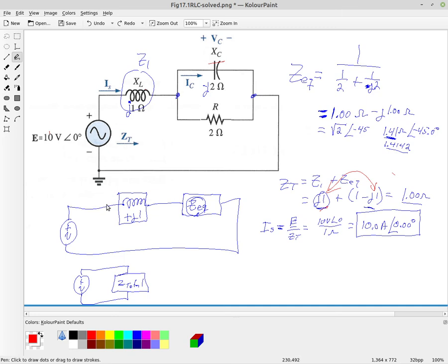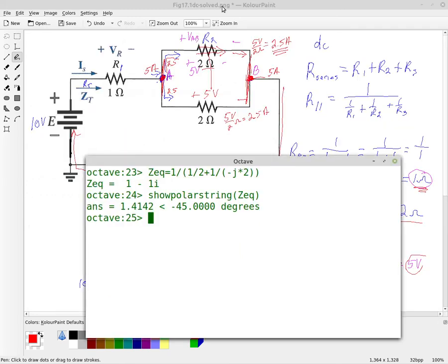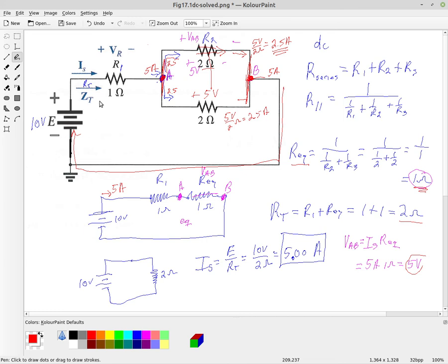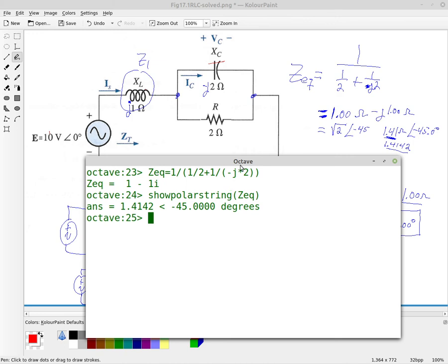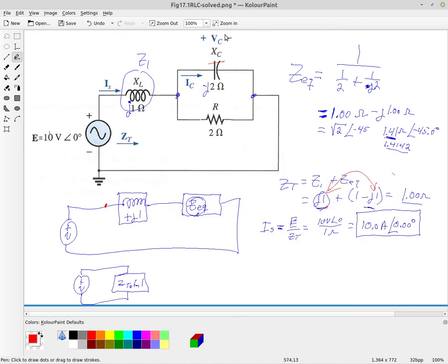Let's find out. We haven't actually done this before, but if you go back and look at the previous circuits, I didn't make a point of this. If you look at the voltage of this circuit, this is our original DC circuit, we did calculate that we had 5 volts DC across these resistors, and since we had 10 volts here, that meant that we actually had 5 volts across this first impedance also. But let's calculate what this voltage is now.